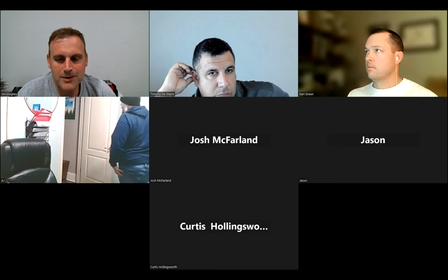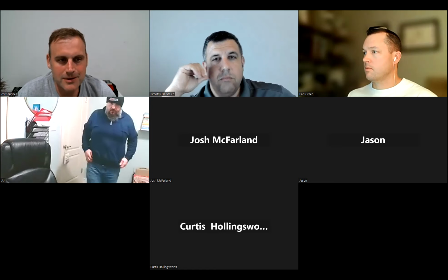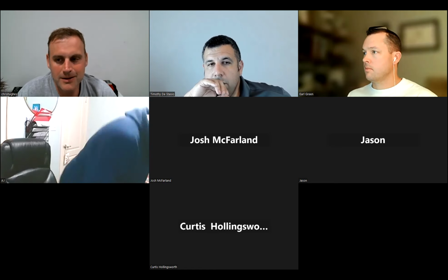I wasn't Neil Comparetto, but I had a good name and I could charge a super premium for doing my installs. But they knew when I came in, it was load calculation, blower door, duct leakage test, install, commissioning on the way out. That's what you got. That was my turnkey, super whammy bammy thing. And if you didn't want to do it, then sorry. I don't care.